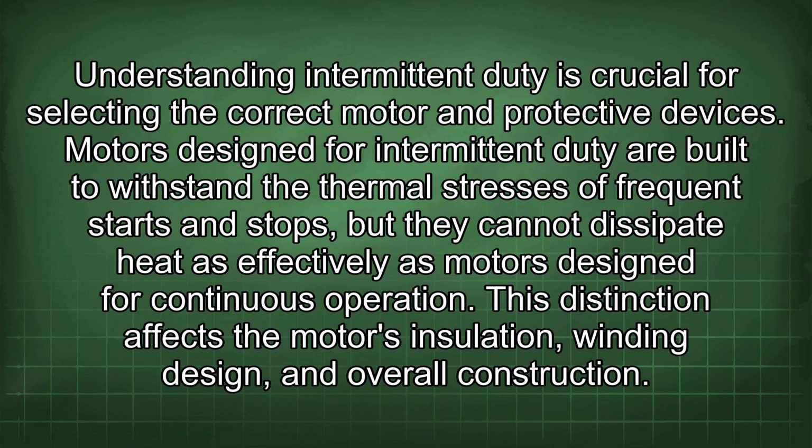Motors designed for intermittent duty are built to withstand the thermal stresses of frequent starts and stops, but they cannot dissipate heat as effectively as motors designed for continuous operation. This distinction affects the motor's insulation, winding design, and overall construction.